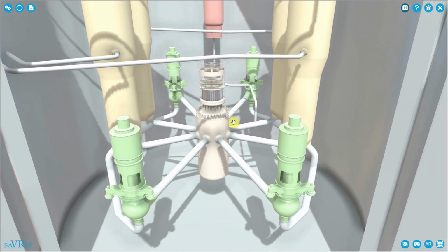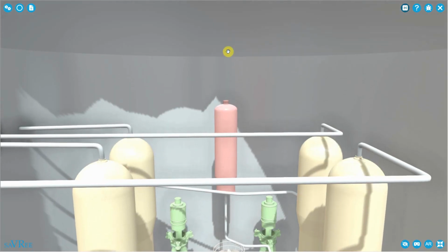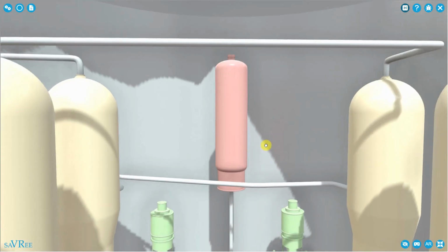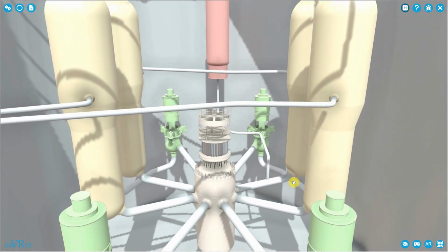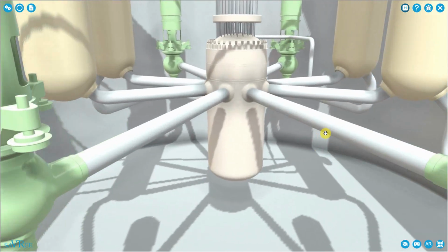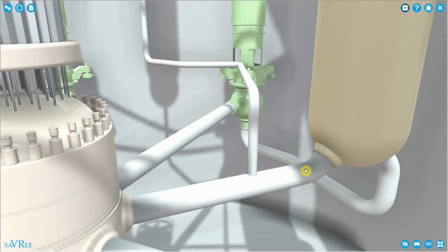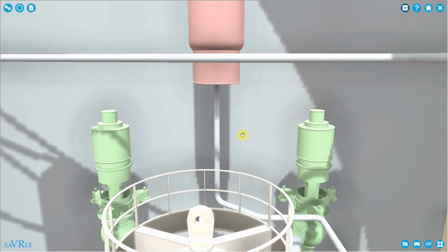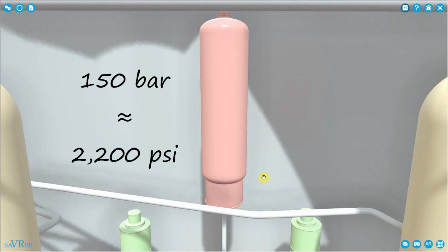We've talked about the reactor, we've talked about the reactor coolant pumps and the steam generators. There's only one other item of interest here, although arguably the whole thing is of interest, and that is the pressurizer. We have a pressurized water reactor, and it's the pressurizer that gives it its name. What we're actually doing is pressurizing our primary cooling circuit. If we come down here, you can see that the pressurizer connects to the hot leg, that is our outlet from the reactor to the steam generator, and we use the pressurizer to maintain the primary coolant circuit at a relatively high pressure, somewhere around 150-160 bar.